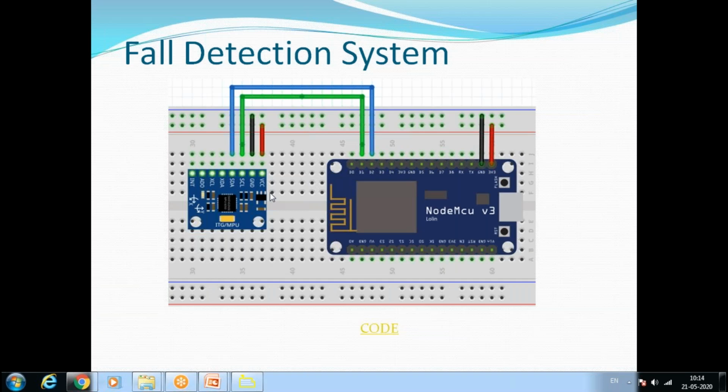When we use SCL and SDA, only two pins are used, but similarly we can connect multiple devices on the same two wires. Here we are using only one device, but if you want multiple I2C devices, they can be connected in parallel to the D1 and D2 pins. How do we activate them? The master provides the signal to the specific device saying that I need information from you. So the master will initiate, and in that case the master has to know the address of each and every slave.